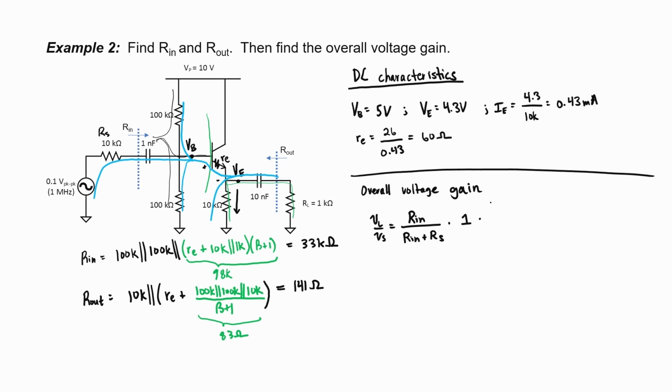In this case, I'm going to be using impedance reflection for the input side, so I'm not going to use it at the output side. For the output side, we're going to have just a simple voltage divider. If I had used impedance reflection, I would have to have another term to add to the emitter resistance, wouldn't I? But I'm not going to do that here.